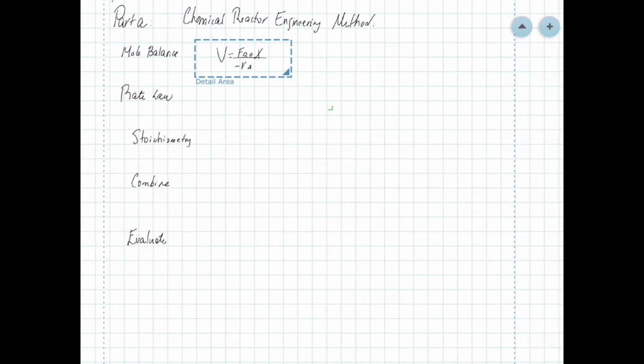That's why we say that a CSTR is typically operating at the lowest rate possible for the reactants that are within the reactor. The rate law for this problem, as we mentioned in the previous example for the batch reactor, is considered to be a first order reaction because the water is in excess, and we analyzed this previously.